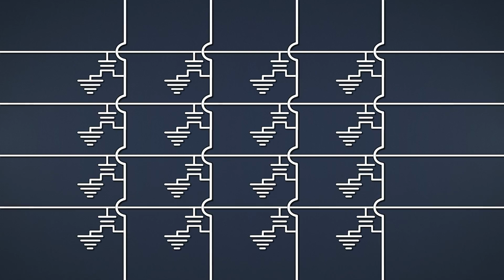Next, we force electrons into our floating gates. Here the yellow gates have electrons in them, and the white ones do not. If we set each bit line high and activate a word line, look what happens. Transistors with a charge in their floating gate are not being activated. That is because we trapped electrons and increased the threshold voltage of those transistors. So the voltage we've been using to activate our transistors is not enough to activate those ones. Therefore, we now have cells that are 0 and cells that are 1.